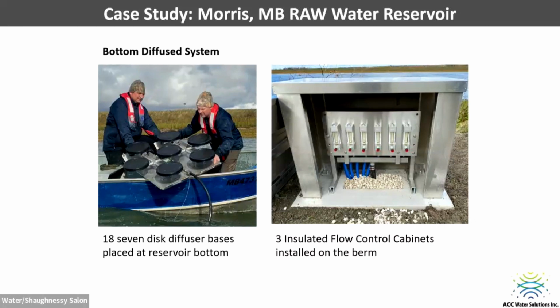We want to make sure that we're giving you stuff that isn't causing you headaches, isn't causing you hassles. A lot of diffusers on the market are a little bit more efficient on the oxygen that they deliver. We chose not to use them because they have to be either pulled up and cleaned with an acid or fully replaced about every 5 years. So when we do the cost benefit analysis, we're like, maybe it's better that we slightly lose efficiency during the first year or two of operation compared to the competitive model, and in exchange, not create a whole bunch of operational hassles for the operators.